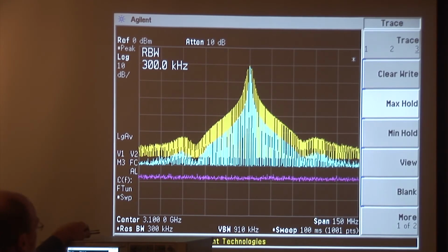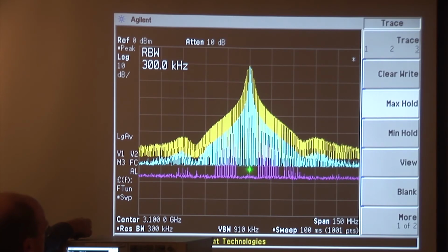Now in this more narrow bandwidth, it's even more problematic. So by the way, in my yellow, blue, yellow, cyan, magenta traces, I'm to some extent replicating the bandwidths that I used when I was looking at the power at the center frequency. Earlier I used 8 megahertz for the yellow. Here I use 3 megahertz, but it's the same concept.